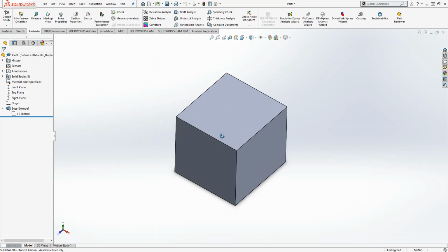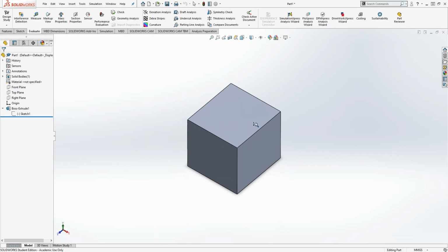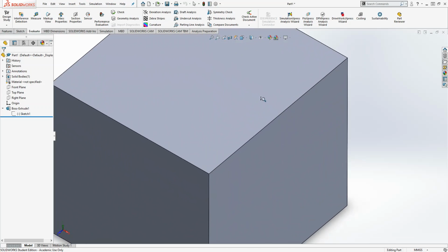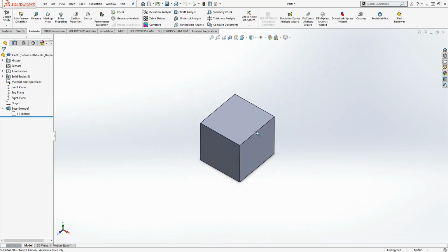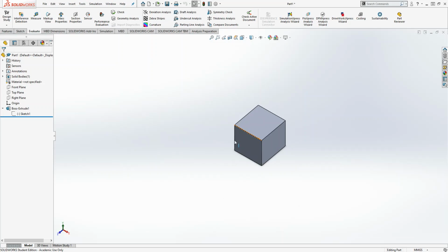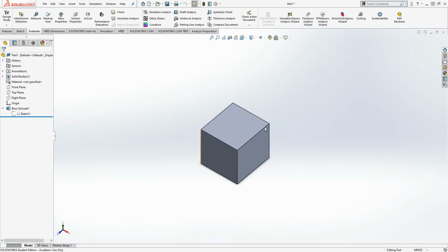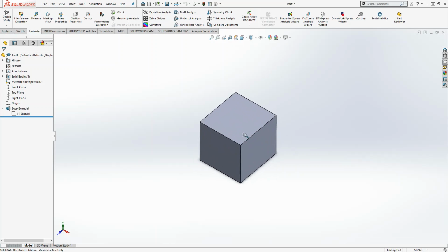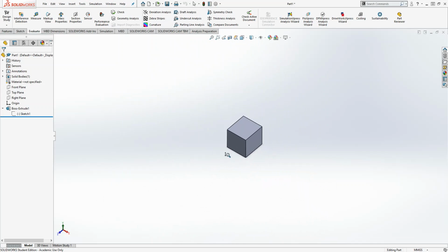So for example, if I take my middle mouse button and just press it down, I get a rotate tool, right? As you can see, I can move my mouse around left or right, it rotates that way, up and down, and you can really get crazy with it and just move your mouse around to rotate this object. Very simple rotate tool, but after a while it's going to be kind of weird moving it like this. So there are different options that you want. We can use the Shift, Control, and Alt keys to alter the way we're currently using SolidWorks.